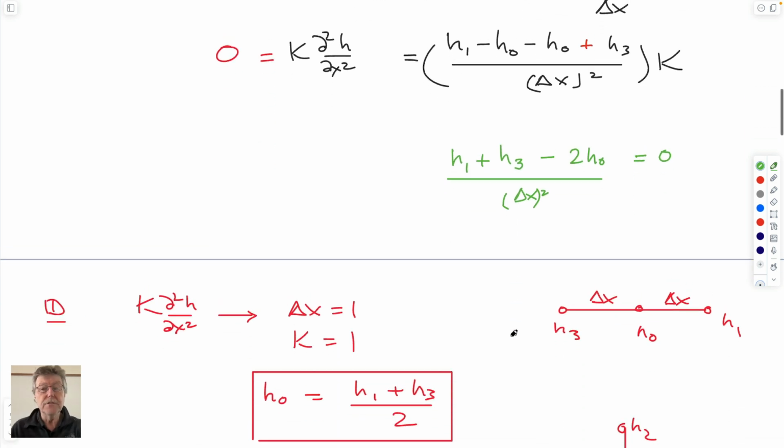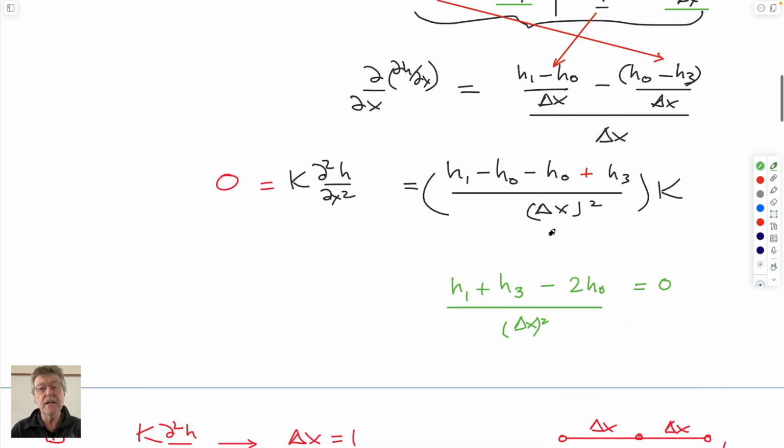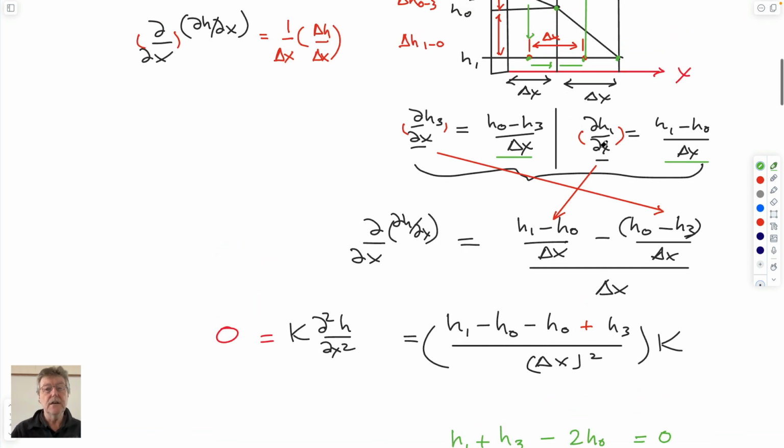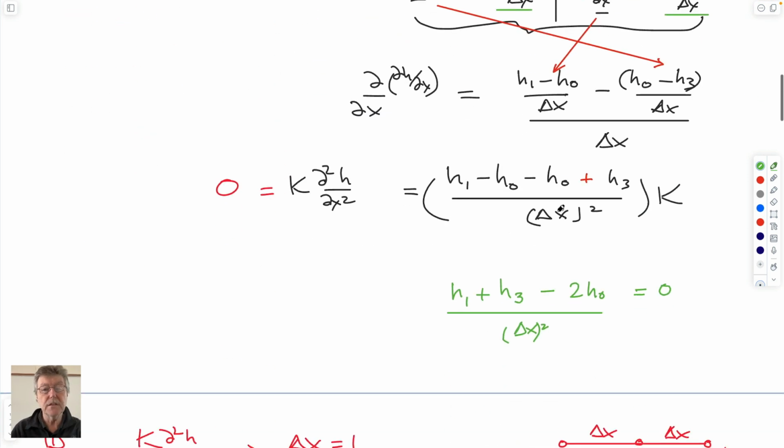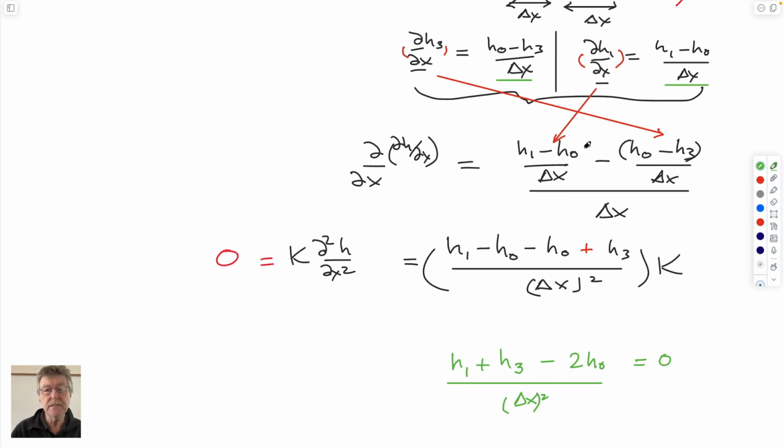And so the other thing we can do is that if we make these delta x's along the nodes, if you like, within our mesh, the same separations, then we don't care what those are, because we can only move from this case to this case if we make delta x's the same, both upstream and downstream, right?